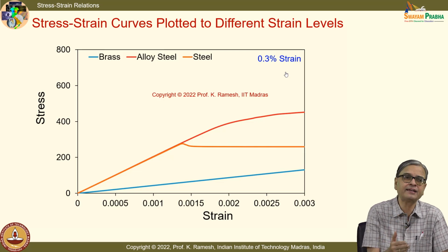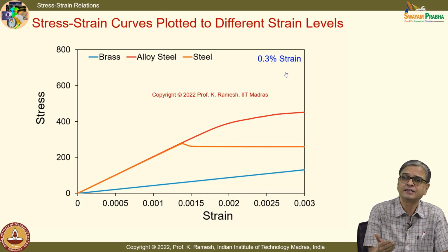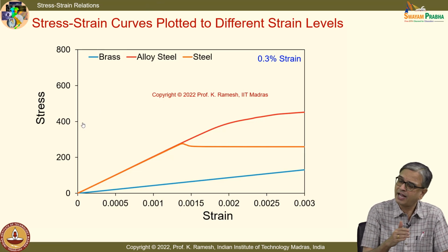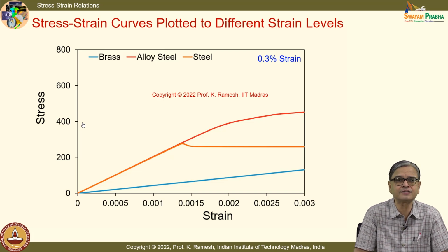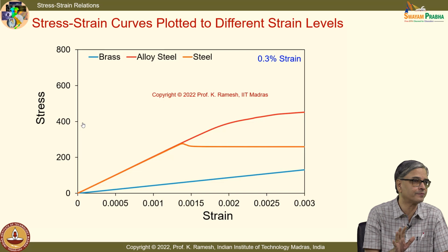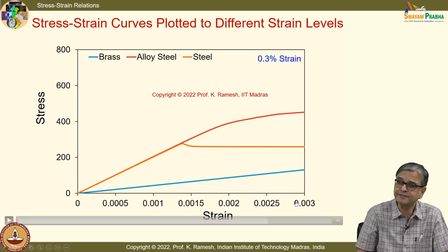The same data looks different. Suppose I also change the y-axis parallelly, I would have a different picture. One of the lacuna I find in many of the books is they give stress strain graph without labeling the axis. While discussing the constitutive relations, they give a general picture, which is not sufficient from understanding point of view. You should also have to associate with these numbers. So when I look at in the x-axis a very small strain, all these approximations are valid.